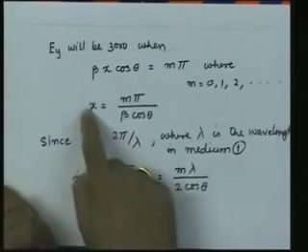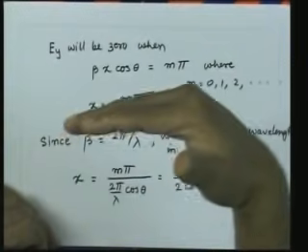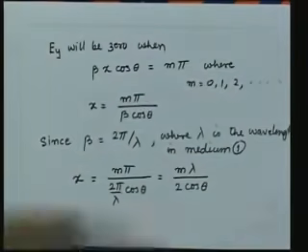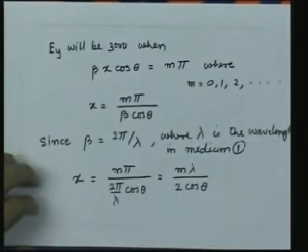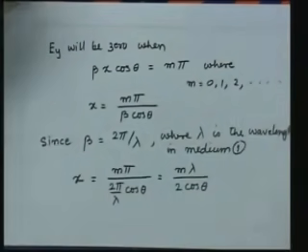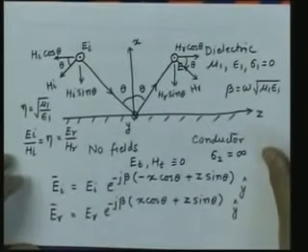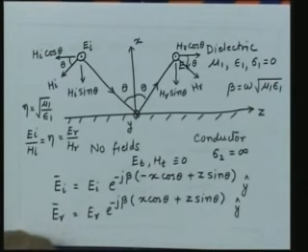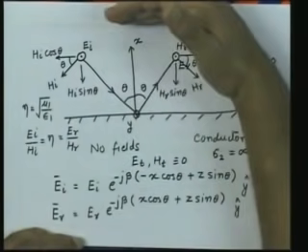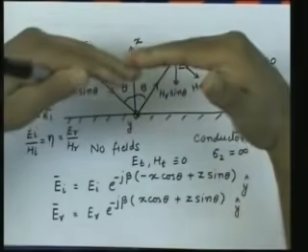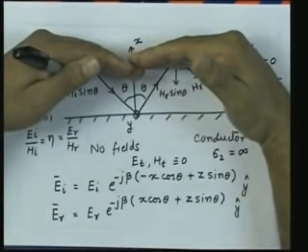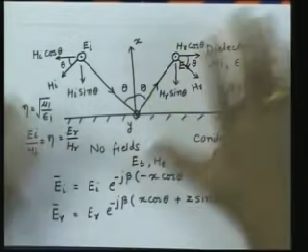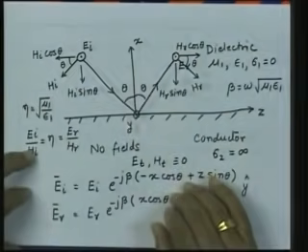That means at this value of x, if I insert a conducting sheet of infinite extent like this, the fields will remain unaffected. What that then means is that not only the value x equal to 0 where the condition will be satisfied, but I will have another value of x, and another value of x, at which if I insert a conducting boundary like this, these fields whatever we have got will remain unchanged. I will get the same field distribution.